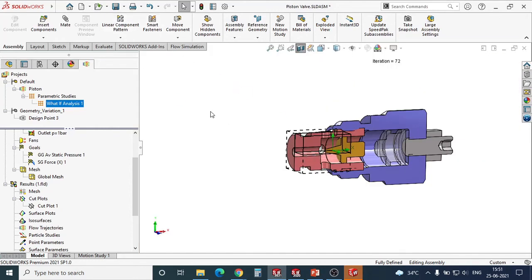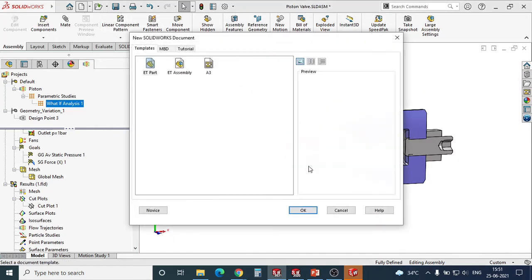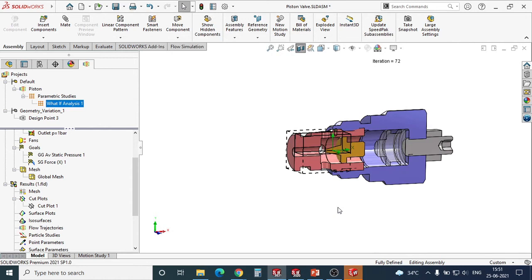Now if I talk about SolidWorks, and compare it with Creo, SolidWorks comes with part, assembly and drawing, and it has full associativity with each other. If there are any revisions coming inside your model, once the drawing is released, any edit that you do inside your 2D drawing can be reflected in your CAD model.